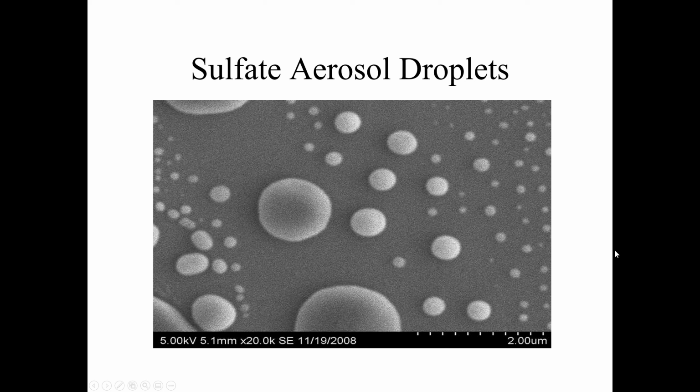When I was working on my master's, we did a lot of work with the PM 2.5 and aerosols. So here I'm analyzing some unknown material on a sampling filter. The material is actually sulfate from sulfuric acid. If I run the EDAX, all it shows is sulfur and oxygen for these droplets. I did coat this. These aerosol droplets are physically bound to the substrate, so even under high vacuum, they don't outgas or evaporate.